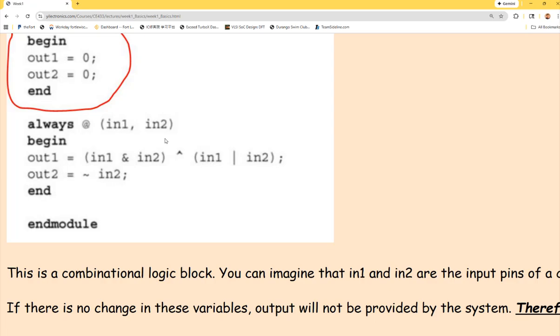Never think about the whole thing which you are writing up in Vivado or Vim will be executed from top to bottom as instructions. It's not, because these are hardware, not software. So once this is synthesized by Vivado, it's like a picture or image of circuits, done. It's done on the chip. Okay? So the question is, are you able to write a piece of software for hardware in FPGA?